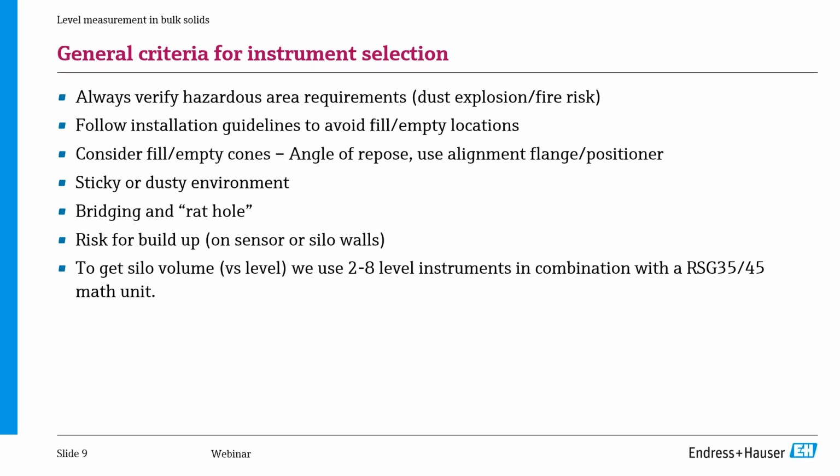The second point that we really must keep in mind when we talk about level measurement in solids is to really follow the installation guidelines. The installation must be done in a way that you minimize the influence of the geometry and the tank filling and emptying dynamics.